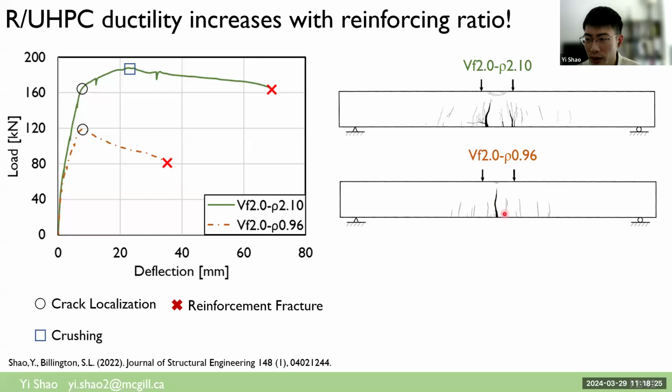So we cannot open an additional localized crack because the flexural stress is decreasing. And then the plasticity concentration causes the steel plasticity to be restrained within a very small region near the localized crack, and we have early rebar fracture here.